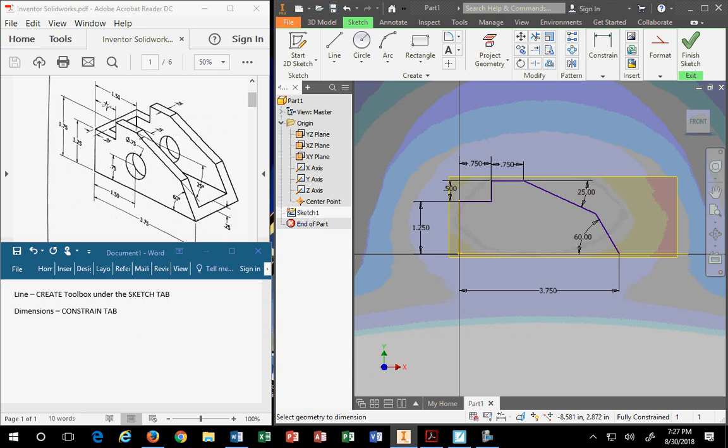So the machinists in the room, don't get mad at me, because I know you wouldn't operate to an 1/8 inch tolerance. But an 1/8 inch tolerance is 1/8 of an inch, right? 0.125 inches, correct? And the 1.5, let's say it has the same tolerance, which is 1/8 of an inch. So hypothetically speaking, what's the maximum variance you can have on the 1.5 dimension? If it had a plus or minus tolerance of 1/8 of an inch, it could be as small as 1.375? No, is it? What's 1.5 minus 1/8?